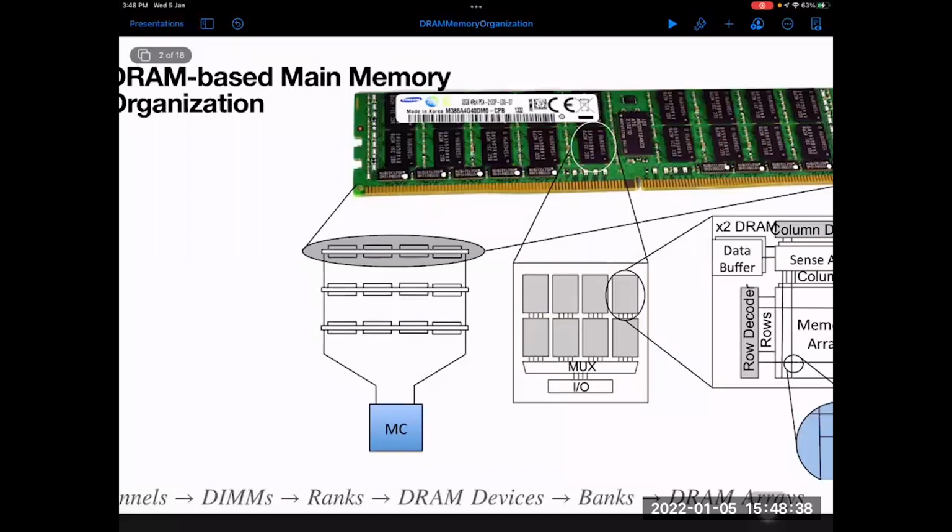And in rowhammer, what happens is you keep on pressing one row continuously, and because of that, it is going to have an impact on the adjacent cells. Once it has an impact, the adjacent cells lose their charge. As a result, the data stored in that cell, if it is initially 0, may now be represented as 1. If it is 1, it may be represented as 0.